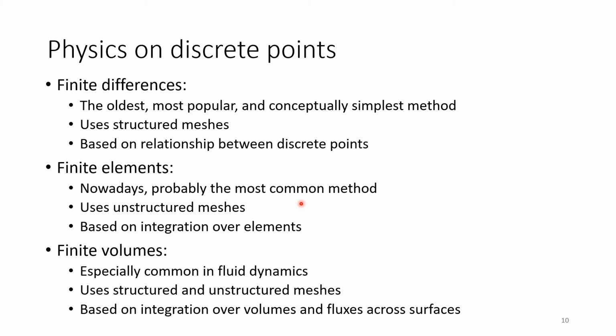The third method, finite volumes, is especially common in fluid dynamics. So it is, well, also a good point to use in groundwater hydraulics. You can use finite volumes on structured and unstructured meshes. This is no problem. And as the name already says, it's based on the integration over volumes and fluxes across those surfaces. And here you already see this connection to the conservation of mass in the groundwater governing equations. So this is really based on this, and it's very conservative and very close to the mathematical concept. So this is why it's especially useful in fluid dynamics.